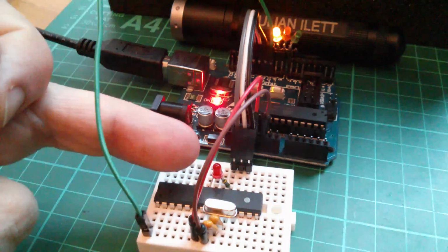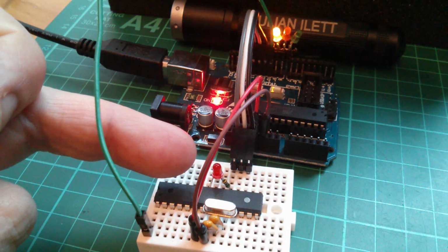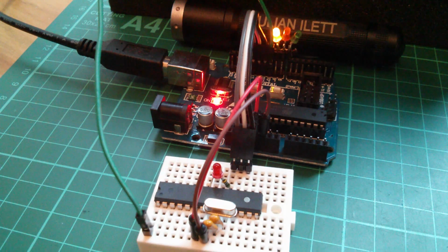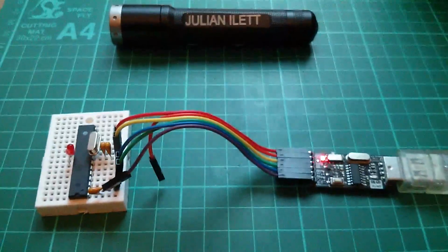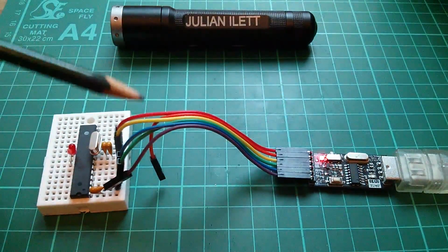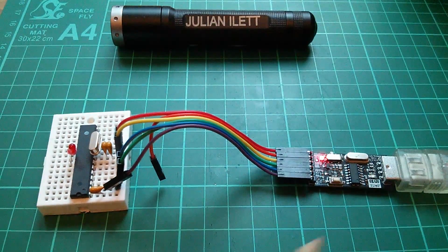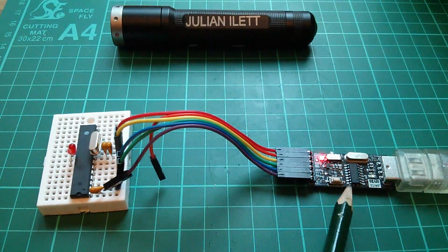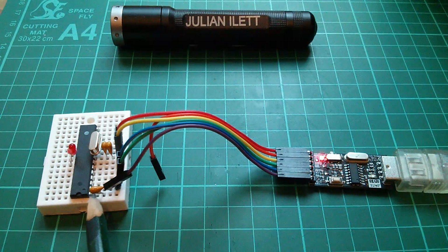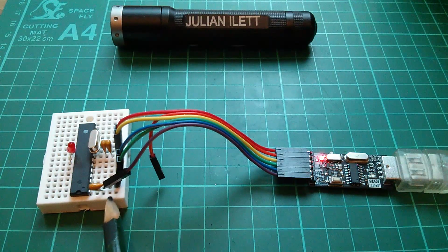Now this LED is no longer flashing, and that's because when you burn a bootloader you effectively wipe everything out of the chip, but that chip should now have a bootloader burnt into it. Now the best way to check whether the bootloader successfully loaded into this chip is to now use this as a conventional Arduino Uno setup. So I've put a USB to serial converter, CH340 here. I've connected up TX and RX and reset. Reset has to go through a 100n capacitor, so I've just bodged that into place. VCC and ground, and let's just do a regular upload and see if it works.